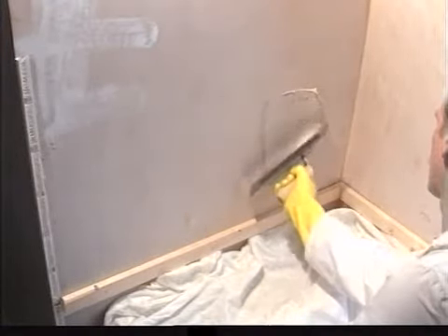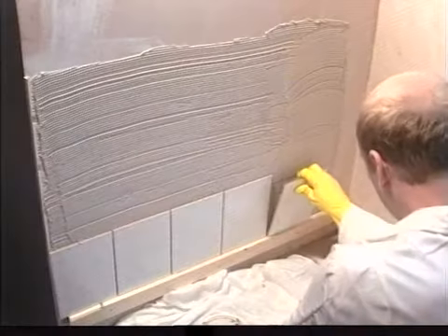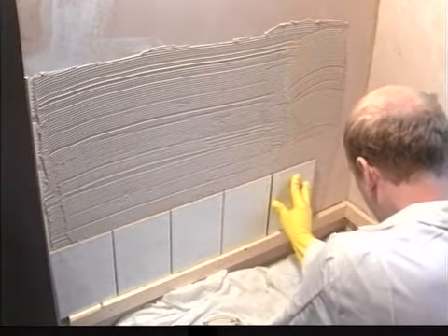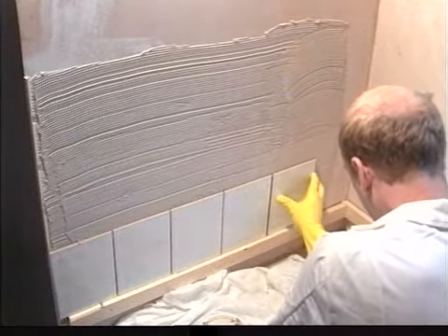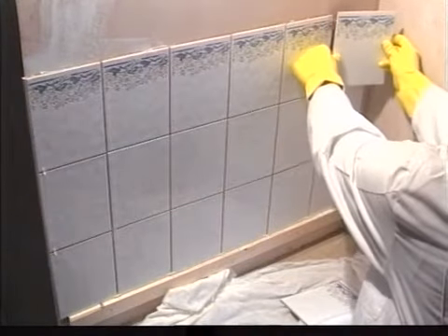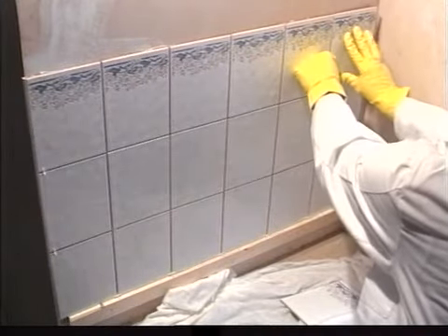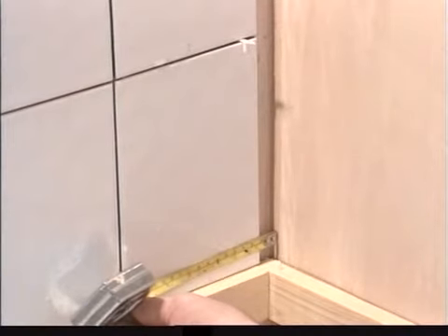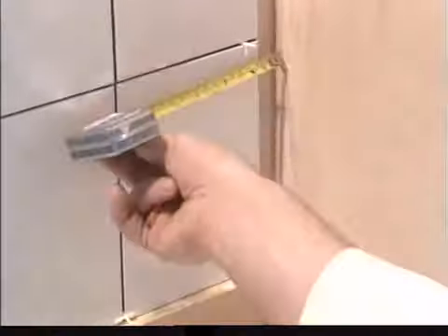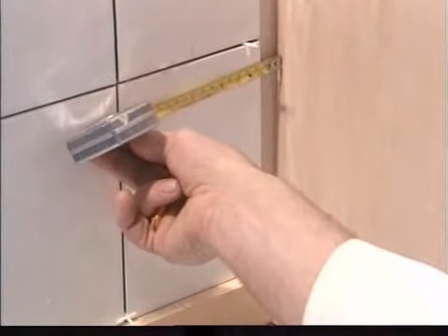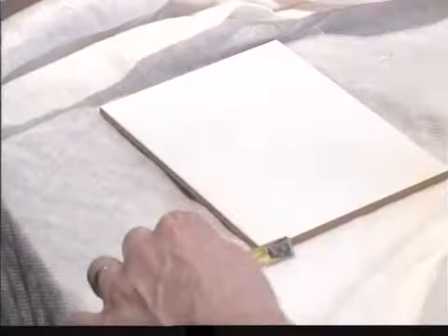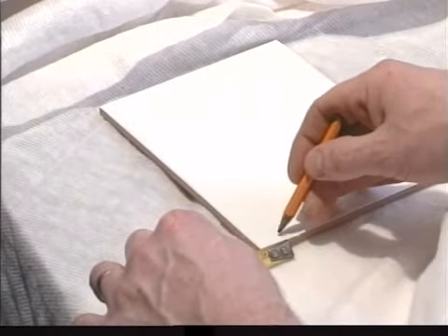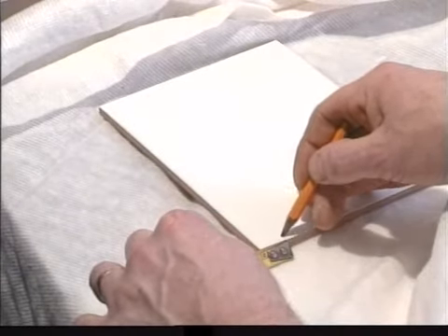Now apply more adhesive as you did before, remembering not to tackle too big an area at any one time. Again, tile along the horizontal batten, working from the tile trim with a full tile towards the corner. Always try to make sure that any cut tiles are in the corners and not on the external angles. Measure the gap between the last full tile and the corner. Mark this measurement onto a full tile.